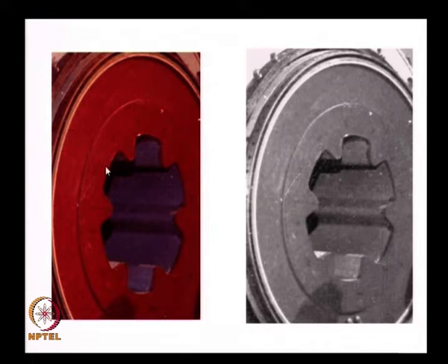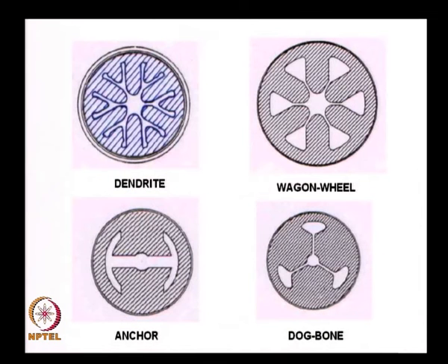The minimum thickness is what we call the web thickness. The same grain I show over here just to make sure we understand. You find that the inner surface has something like a projection here, a valley here, again a projection here. This projection is all along the surface, and the grain burns radially, that means it burns into the grain in this particular fashion, and all along the surface keeps retracting like this. And I will consider a few examples such that we are very clear how to calculate these things.